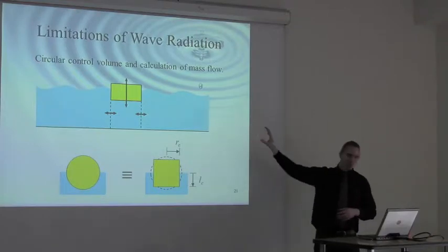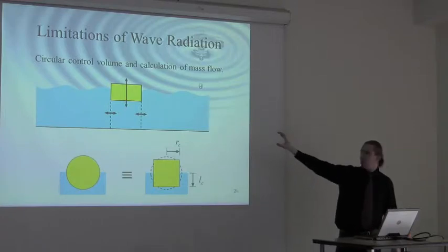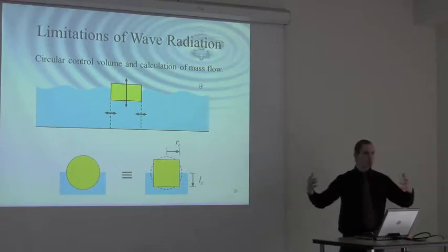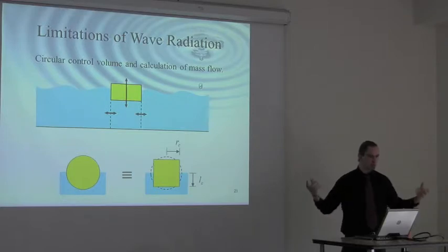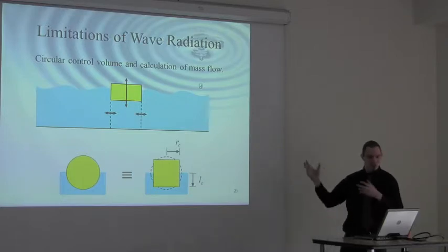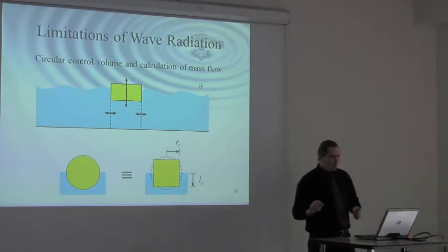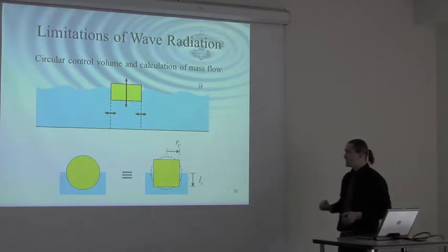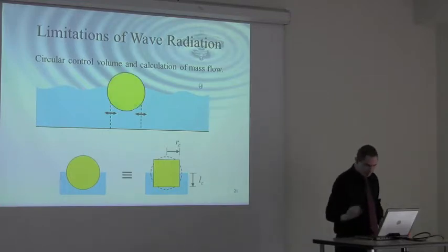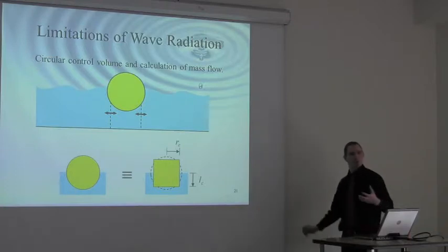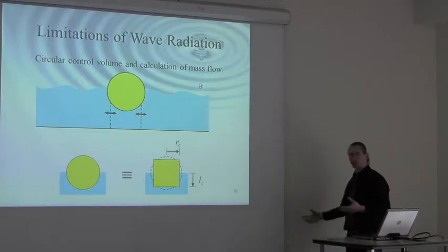And so this way we can relate the volume displaced by the cylinder to the volume displaced by the wave as it moves backwards and forwards, and therefore try and couple the two together. This works well for a cylinder, but what radius do you choose if you've got a sphere or some other sort of axisymmetric shape?